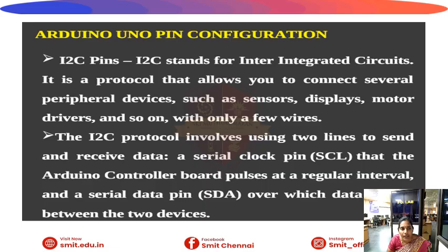Next, I2C pins. I2C stands for Inter-Integrated Circuit. It is a protocol that allows you to connect several peripheral devices such as sensors, displays, drivers, and so on with only a few wires. The I2C protocol involves using two lines to send and receive data: the serial clock pin, SCL, that the Arduino controller board pulses at regular intervals, and the serial data pin, SDA, over which data is transferred between the two devices.